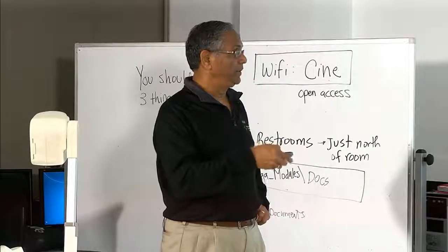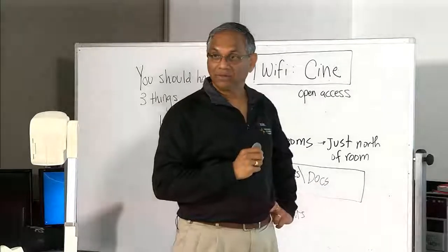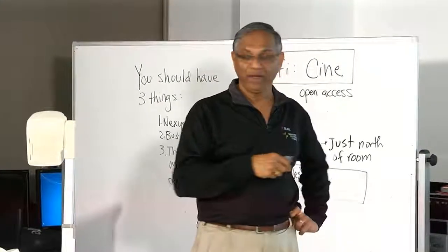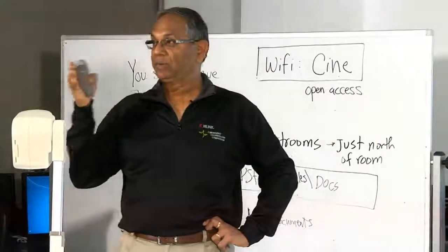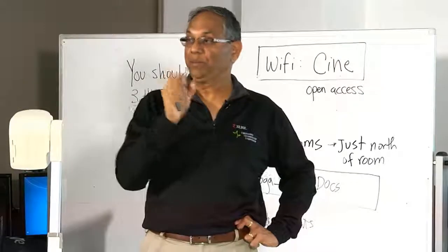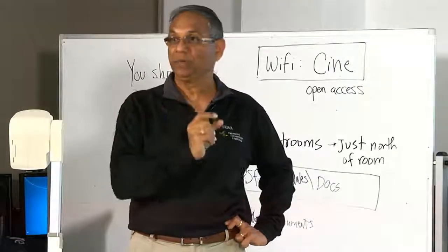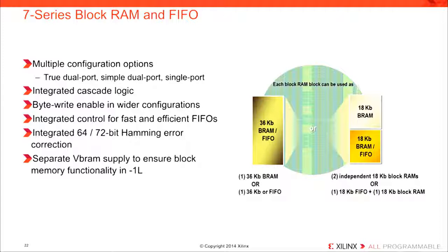And then it is byte write enabled. It means on each BRAM you can have up to 4 byte enables or write enables. It means you can implement a 32-bit bus using one BRAM. You can have 32-bit wide and 8-bit byte, because many processors are all byte oriented. This is something that we have introduced since Virtex 5. Before Virtex 5 it was single, and so the efficient use was not possible.